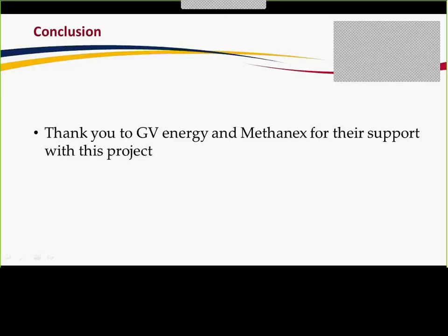But additionally, the higher temperature process required less unit operations for the overall process. So that would reduce the capital cost. We essentially were trying to optimize capital cost to operating costs, and at the time, based on the very high level economic analysis, we had seen that the capital cost at that point would have outweighed the operating cost. Later on, it turned out that this wasn't the case, but at the time, we decided to move forward with the high temperature catalyst.